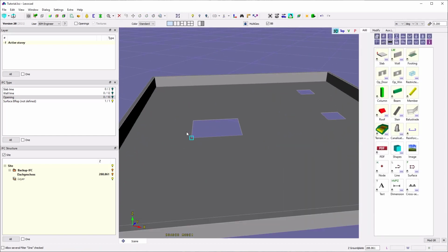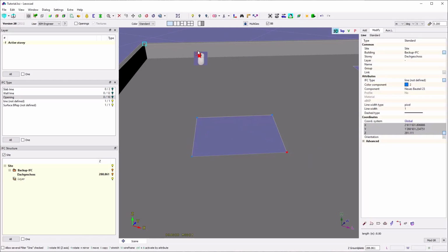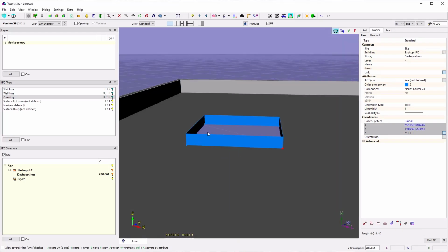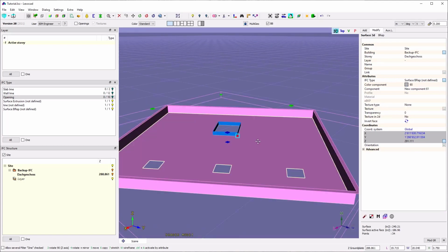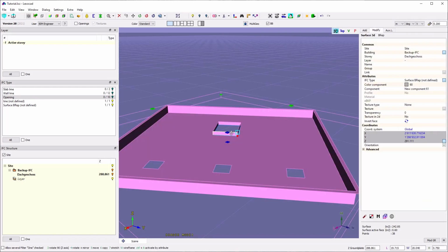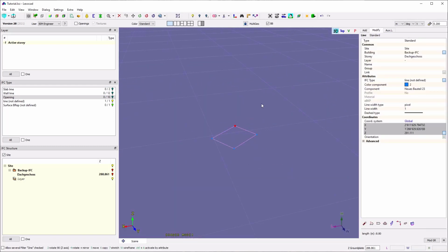Now I want to add here also some surface, but on this side I go with a line, the L button or the L key, activated line, and here I can make an extrusion out of this line. So I get here a div and make it 30 centimeters, and we got also this element. I can activate above, use the D key, and we got it. I can hide this element with the U button. Now we just have the line and I delete it.